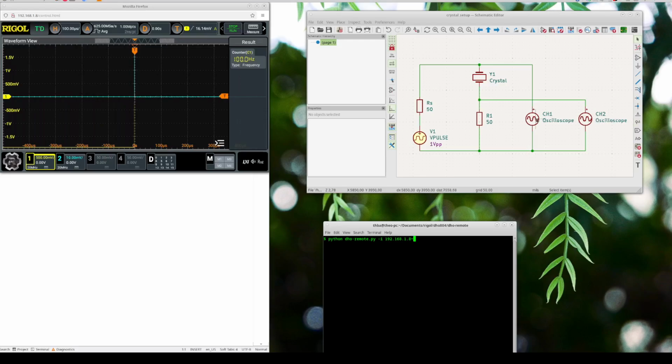This is channel 2, this is channel 1. And because my scope has 1 megaohm impedance, I externally terminate with 50 ohm. So the generator sees a large 1 volt peak square wave signal here, and it sees something here, and I want to know the transfer. So I want to know when it resonates. So this is my setup.